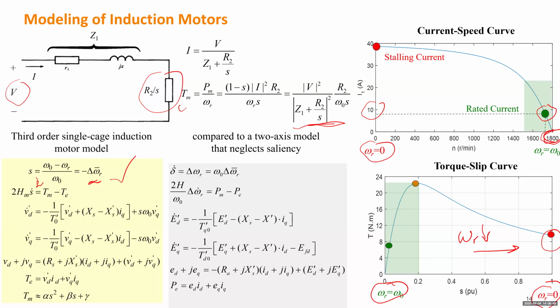The next equation basically talks about how to determine the voltage, the real part and imaginary part of that voltage phasor, right? So that is almost the same as this one to determine the ED and EQ. This equation PE is basically the same as the TE. So lastly, for the synchronous generator, the mechanical power is controlled by the turbine.